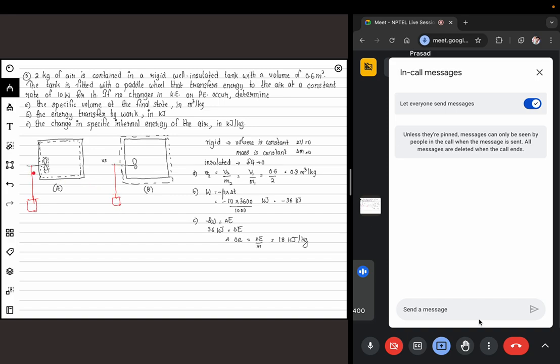But now, if you consider that the fan plus the shaft is outside the boundary, the mass may rise up or down, but that doesn't depend on the system, because it is not part of the system. So the interaction between the fan and the system, that is the gas inside, is not because of work but because of heat. As the fan blades rotate, because of the friction between the fan blades and the air inside this container, heat will be generated. Here the boundary is between the fan blades and the air, where there is no work transfer, but there is heat transfer.